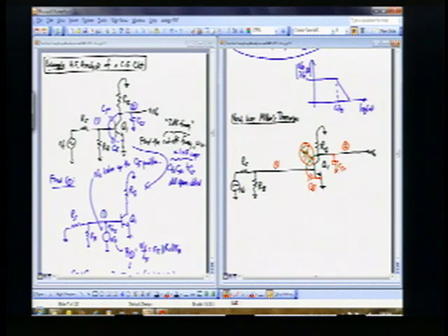Okay, and let's turn it into two capacitors. So one capacitor in shunt with the input, and one capacitor in shunt with the output. Okay, and the values of these capacitors are determined by Miller's theorem. So this capacitor now becomes equal to C mu times 1 minus whatever the gain is, A sub V. So that's the gain across Q1. To be explicit, from base to collector.